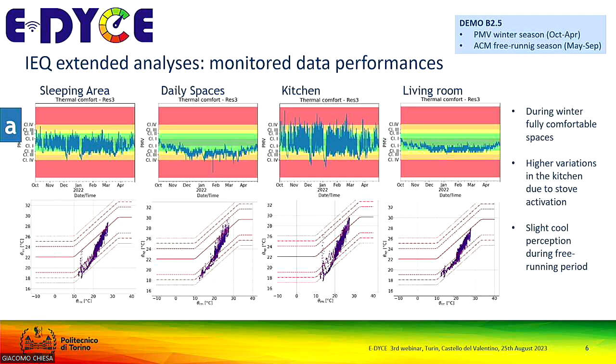And it's immediately evident that we have 3 spaces that stay in comfort, 2 are less used, and so the tenants correctly manage it, allowing slightly cold comfort conditions but reducing energy needs. But it's immediately evident also that we have a room with a very high variation that is not the one that is reached by the radiator system. And we will see why.